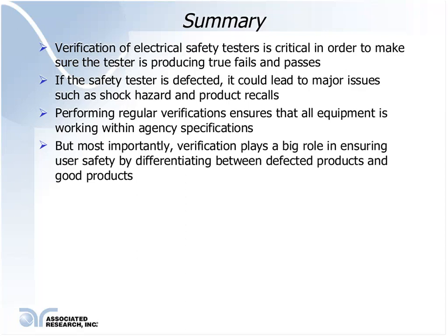Using a resistor in series with the output of an electrical safety testing instrument will assist in validating measurements and ensuring that the failure detectors are functioning properly. Also, setting up a fixture with a series of resistors, as we discussed, just like the TVB2 box, with calibrated resistor values, takes the verification process one step further.